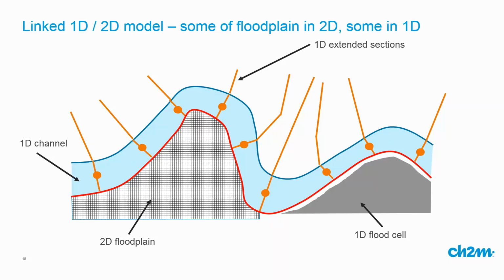So we've used a 1D flood cell for that, and then perhaps on the north of the river there, it's perhaps just agricultural land. There's a sort of a general flow down the floodplain there. We just don't need the detail that a 2D model would give you, and the 1D model can still be run, can still produce a flood map, and it'll be good enough for what we want here. So that's how you can select different approaches for different locations. And yeah, using things like the Flood Modeller software, you can do all of that. You can have all those different methods within the same model.